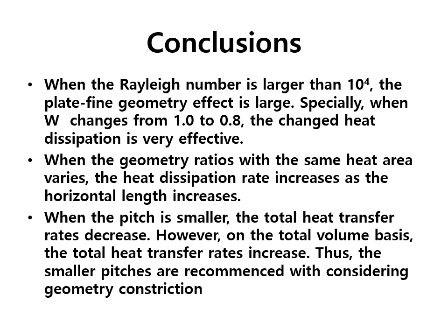When the geometry ratio with the same heat transfer area varies, the heat dissipation rate increases as the horizontal length increases. When the pitch is smaller, the total heat transfer rate decreases. However, on the total volume basis, the total heat transfer rate increases. Thus, smaller pitches are recommended, considering geometric constraints.